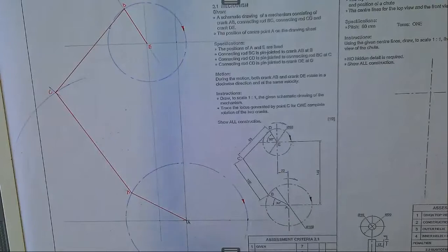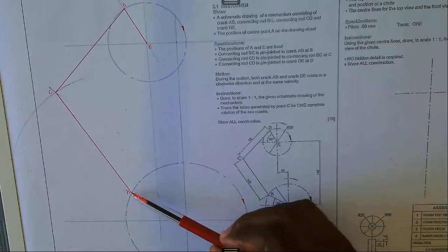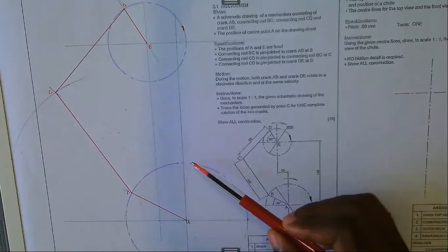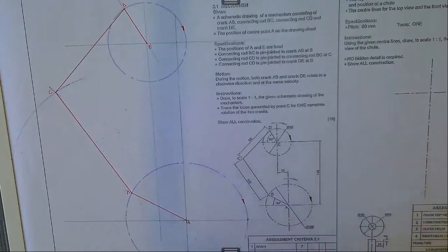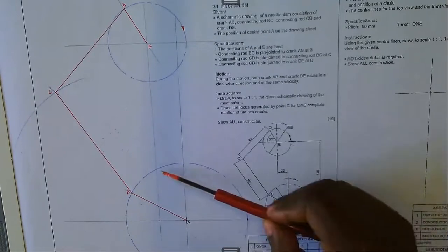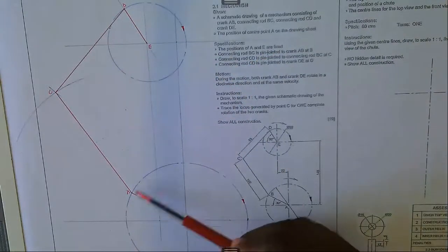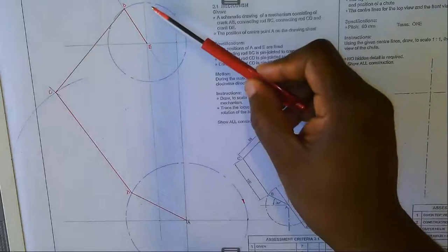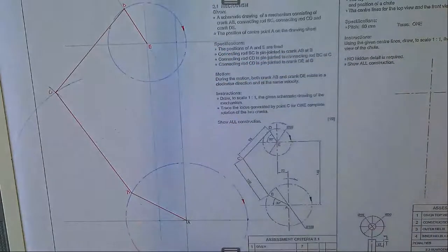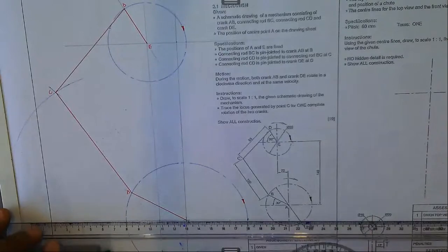So what we need to do is to make sure that we can move point B at certain intervals. Remember, when we are talking about certain intervals, we divide the circle into a number of equal parts. In this case, we are going to divide this into 12 as well as that into 12. So that when we talk about B1, we also talk about D1, both in clockwise direction. But before that, let's define the center lines.